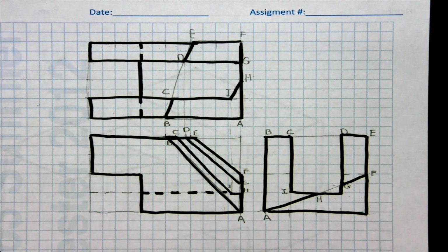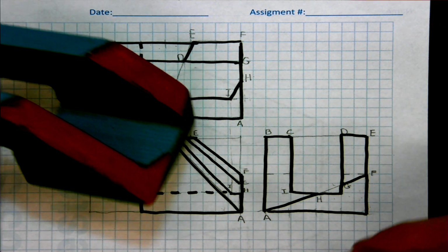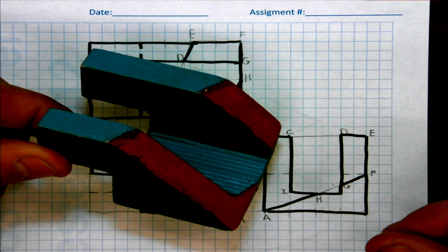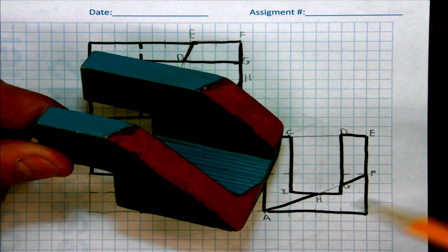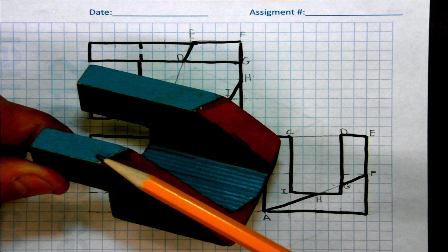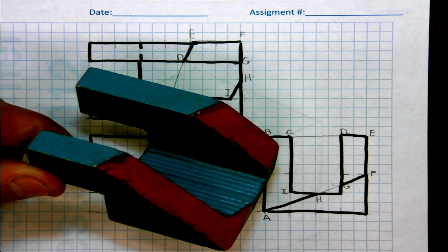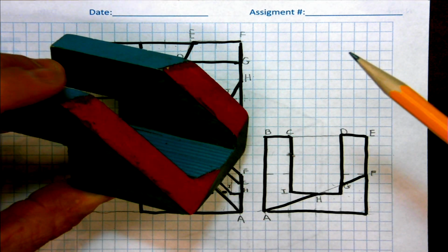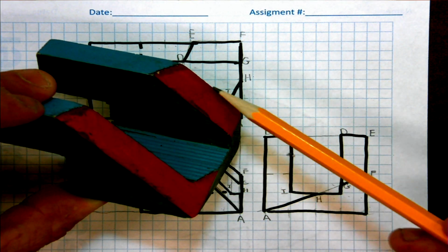If you take these things and break them down into simplified steps, these problems fall apart. You look at this and think, whoa, how am I ever going to sketch this? Well, it's not that difficult if you break it down and think about the relationships. This oblique plane, wherever it hits a horizontal plane, has to be parallel. Wherever it hits a profile plane, that and that have to be parallel. Where it hits a frontal plane, that and that have to be parallel.